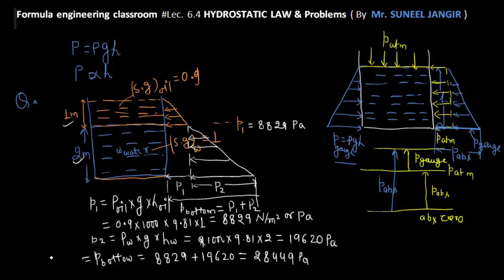This value is actually a gauge value, because we are not adding the atmospheric pressure in this one. So through this hydrostatic law we can easily calculate how much pressure the fluid is exerting over the bottom of the container and all these things.